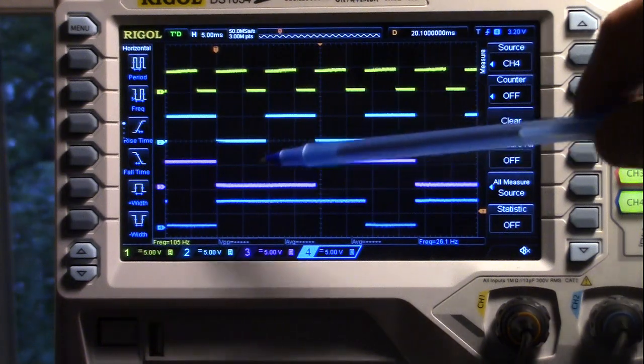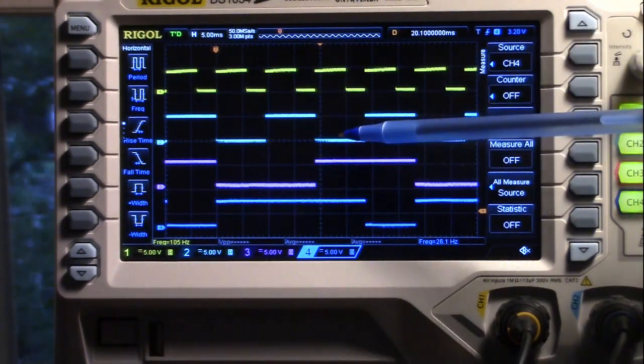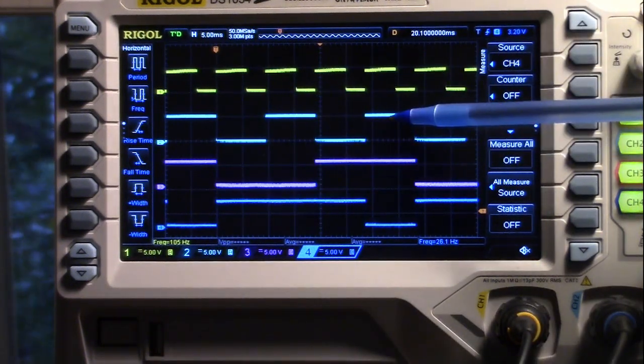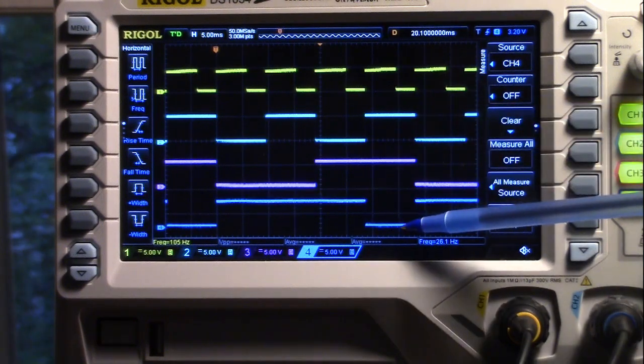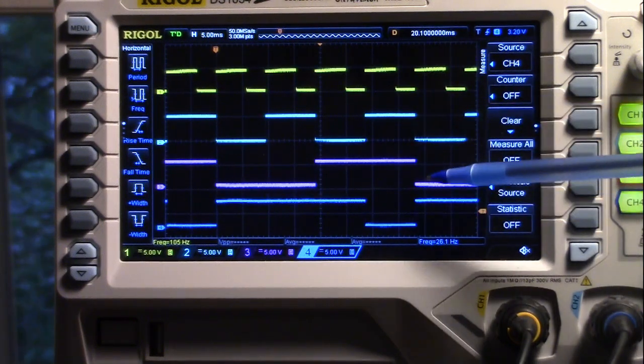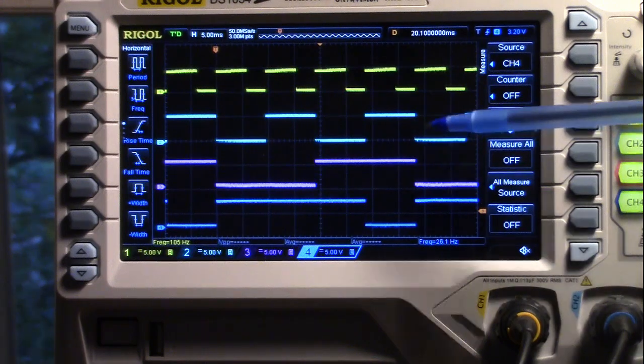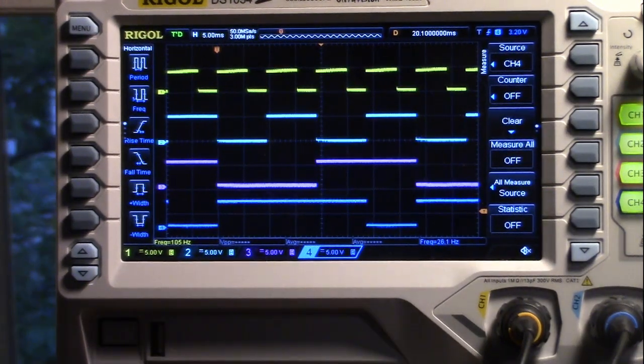So our counter starts out 0, 0, 0, 1, 1, 0, and then it goes to 1, 1. We NAND that together, go low, but we don't reset until the next rising clock pulse back to 0, 0. So counting 0, 0, 0, 1, 1, 0, 1, 1, back to 0, 0. That's a divide by 4, not a divide by 3.